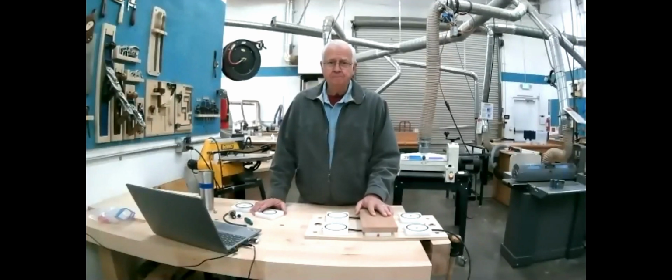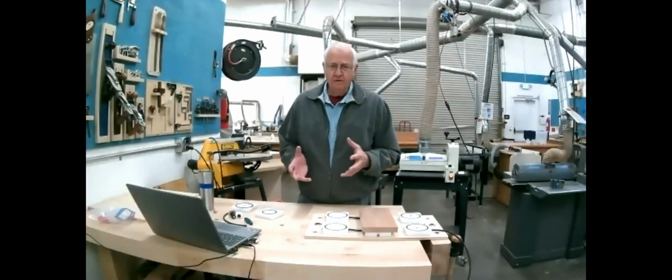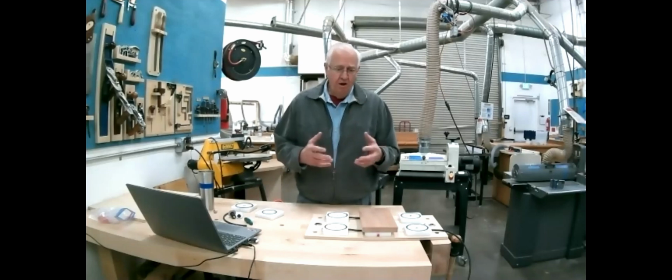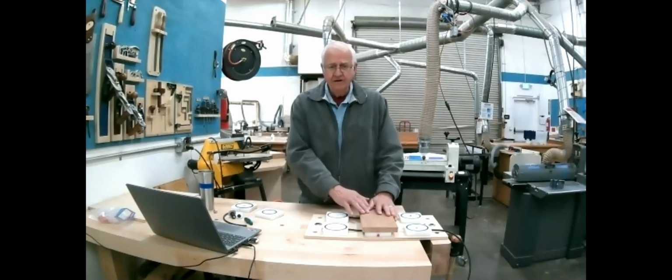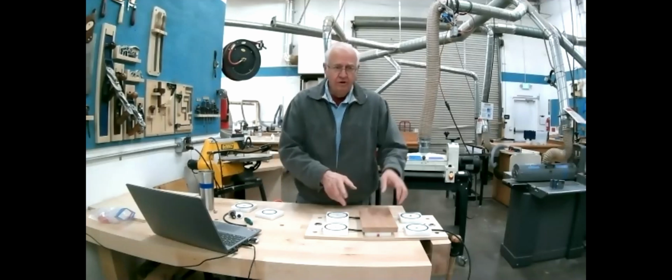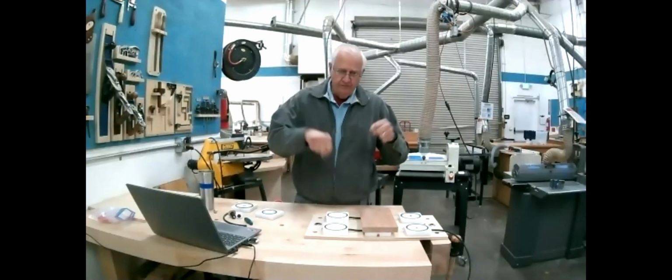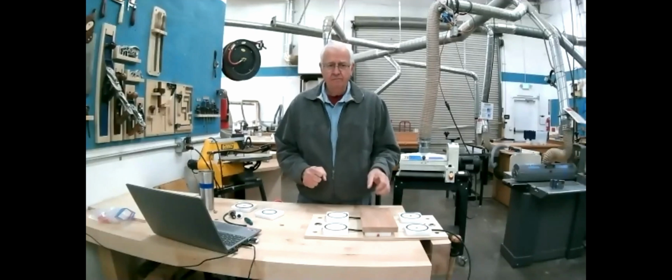So why would you vacuum clamp? There's quite a few reasons you do it. For one thing, it's really handy if you're making multiple parts. You have to put something down and sand it and then move it around, or put down another part that's identical, and you don't want to have to clamp and put pieces down. It just takes extra time. If you can just move them in and out real quickly with a vacuum clamp, it makes a big difference.